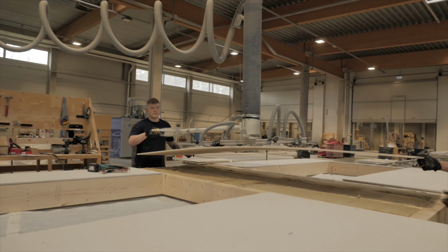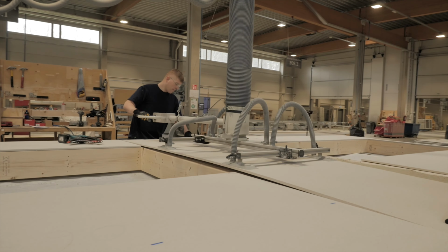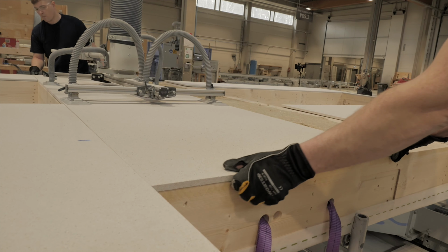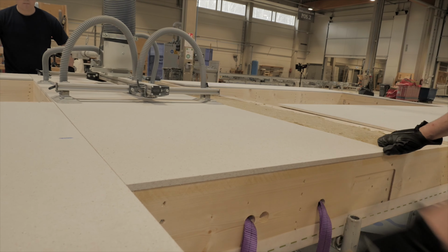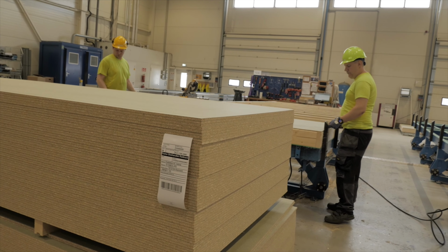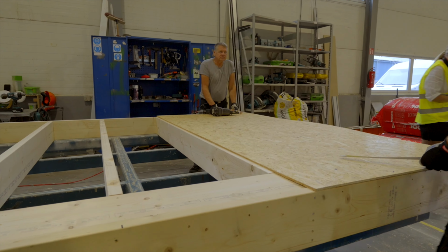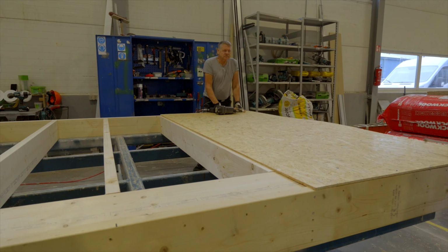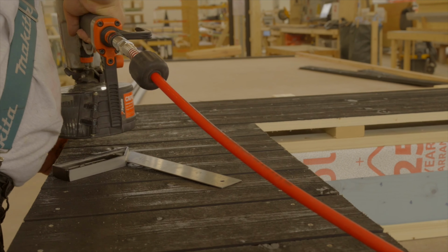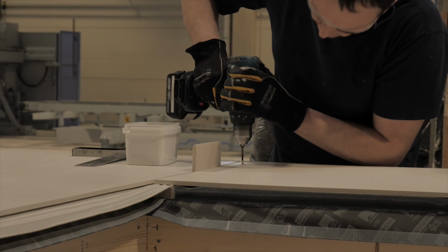After checking the measurements of the previously assembled frame element, it's time to start installing different building boards that can protect the construction from fire and give stiffness to the element. Boards that go on the room side of the element can be plasterboards or wood-based boards. There are also mixed solutions, where the wood-based board is under the plasterboard, thus helping to stiffen the walls and make the wall stronger. And in the case of the exterior, wooden cladding, cement-based or composite material boards can be used as the outer layer.